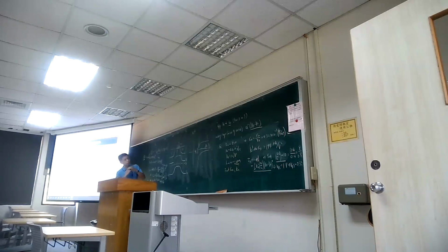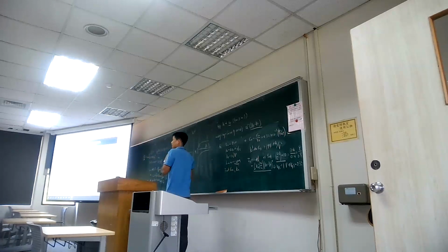So when you bend this down, you will identify what happens to the Fermi level. It will go up, right? It will go up to the intrinsic level. When you bend everything down, you can see originally the EI, the intrinsic level, is above the Fermi level, but along the surface we bend it down. So you can see the Fermi level is above the intrinsic level. So you can see the bend down behavior. Not easy to do. Okay?